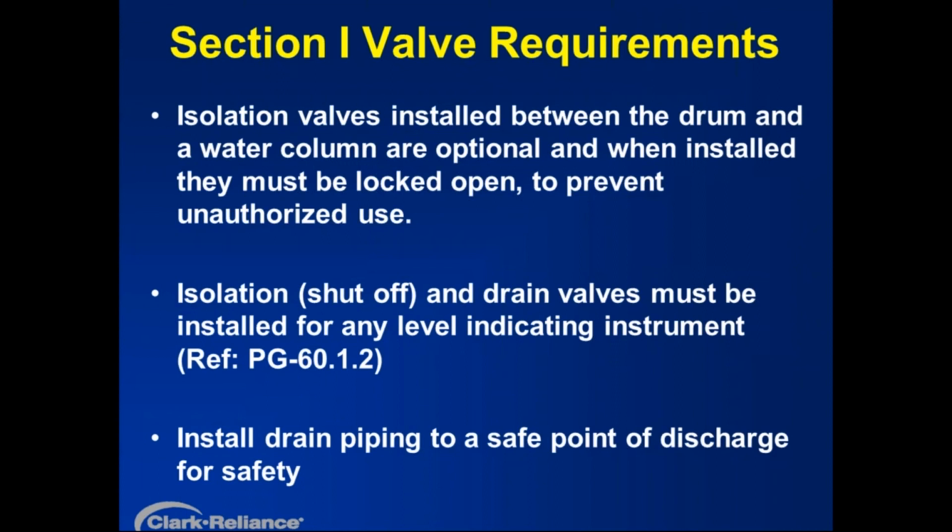However, if they are used, they must be physically locked open to prevent unauthorized use, and someone in the control area would be the main responsible party for that locking device. All right. Also, drain piping coming off of any level instrument should be routed to a point of safe discharge.